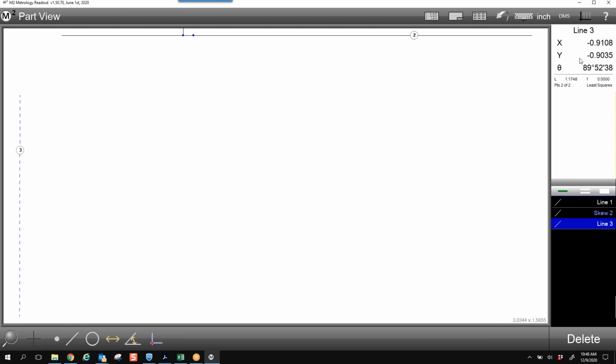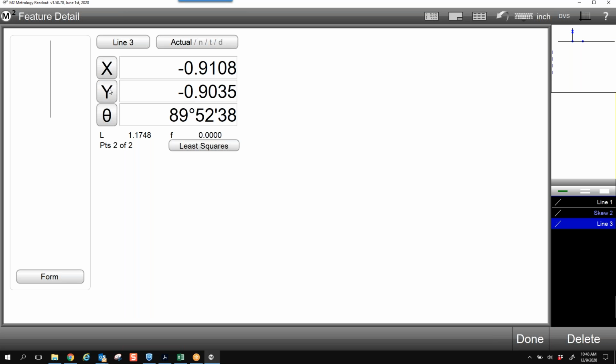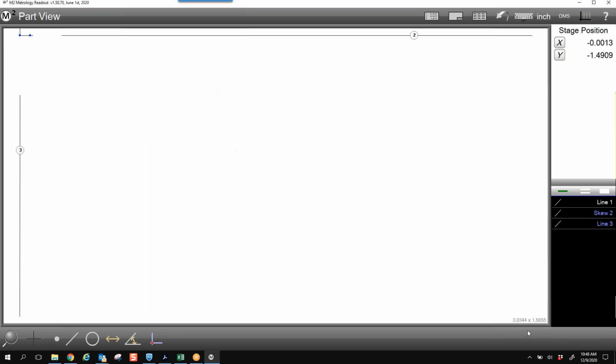So what I want to do now is come back. I'm just going to click on my DRO right here. I want to hit my X for 0. Now see up here, my datum. My datum is at the corner of this line and this line. That's on my part. You guys with me on that? Yep. Okay.